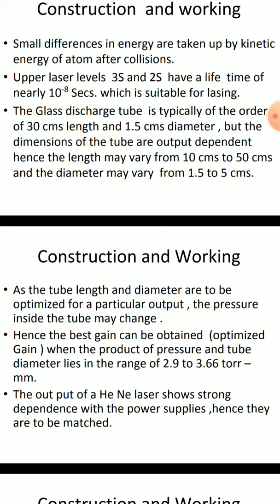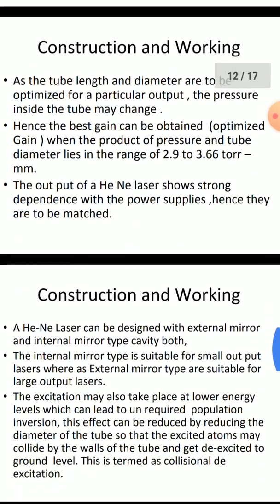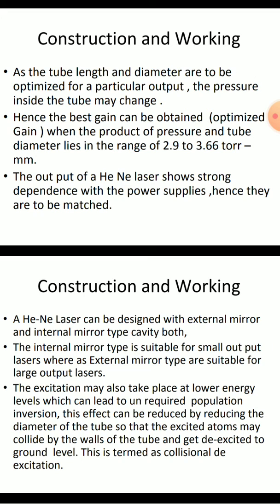The output of a helium neon laser shows strong dependence on the power supply. Hence, they are to be matched. It is important to design a power supply for a helium neon laser. A helium neon laser can be designed with both external mirror and internal mirror type cavities. The internal mirror type cavity is suitable for small output lasers, whereas the external mirror type cavity is suitable for large output lasers.